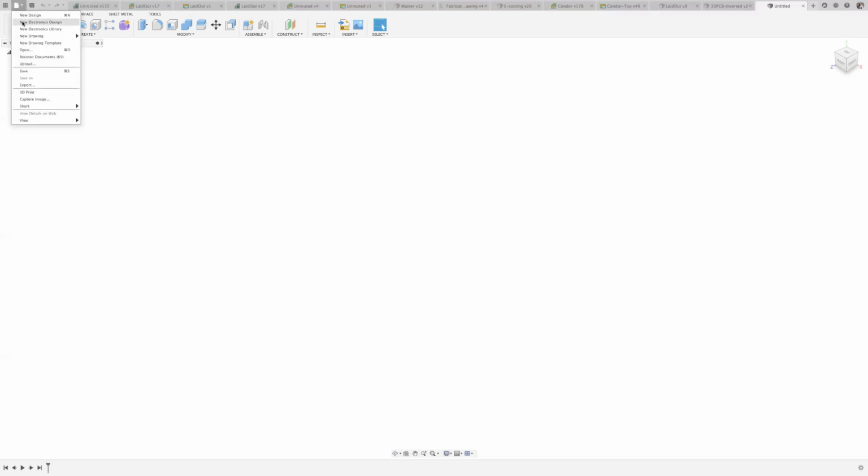To access the electronic design capabilities of Fusion 360, we're going to click on the File pull-down menu and select the option New Electronic Design. Remember, while I was talking on the slides, we said the schematic and the circuit board always keep annotation. It is because of the electronic document. This keeps track of any changes between the schematic and the board, taking effect on both of them in real time. So if I add parts, delete parts, connections, and so forth, this is where everything is kept synchronized between them.